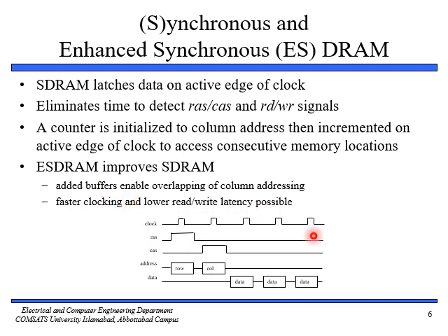So we are going to combine this with our previous strategy so that there is some overlapping. If we use a buffer, we can compute the next address while we are reading or writing the data in the cache, as we have done in the previous slide. So that was about enhanced synchronous DRAM. We are using a clock here.